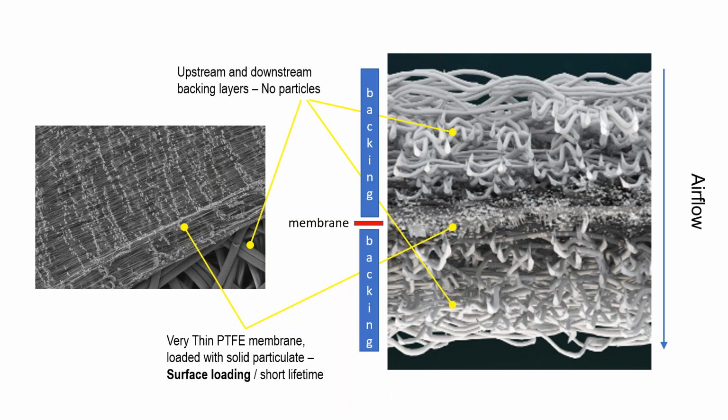As a result of that, PTFE is fairly durable. It's forgiving of handling as a result. However, its efficiency falls quite low because the membrane loads very quickly. Even if it does have a very low pressure drop to begin with, it quickly builds and soon is out of service. So again, for a fairly expensive filter, it's compromised very quickly.